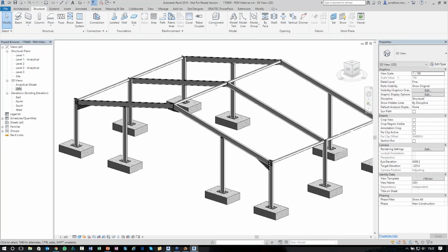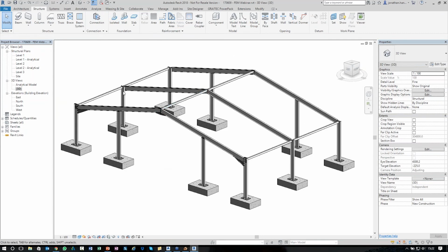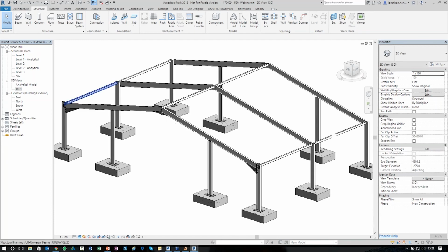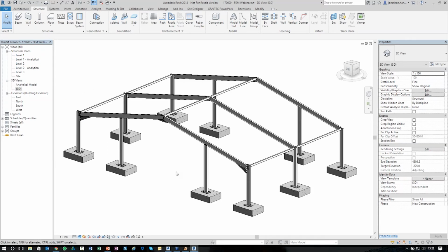This will create, some of you are probably quite familiar with an SMLX file. So we're going to go with the Revit out, save it, we're going to replace what we've got, and the system will create a transfer file that works between Revit and Advanced Steel. So we're going to create an SMLX file, which is a steel markup language.